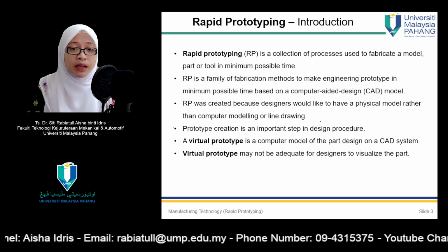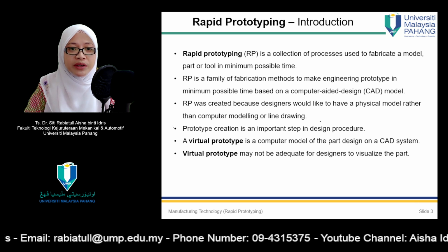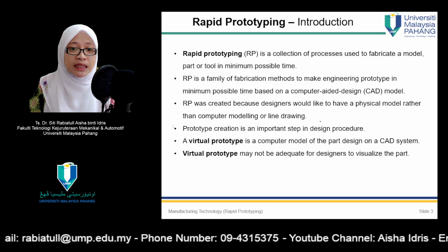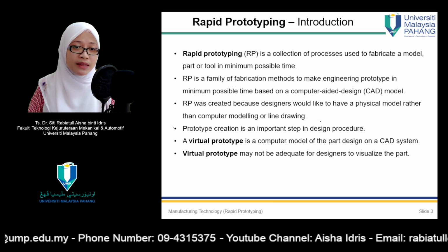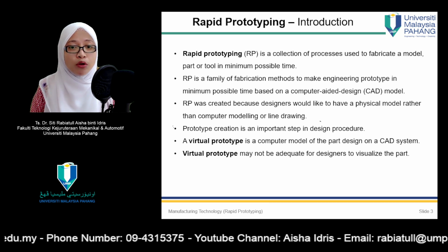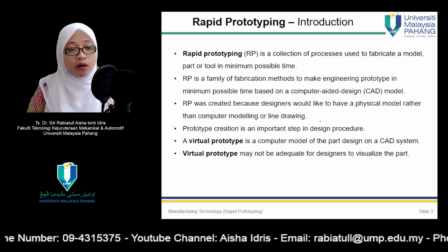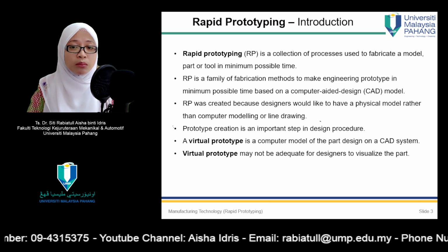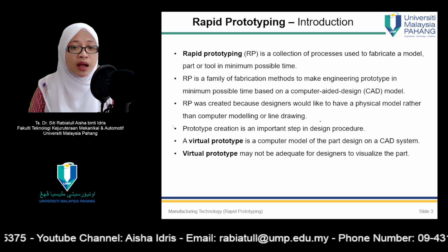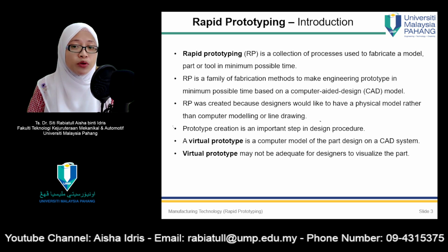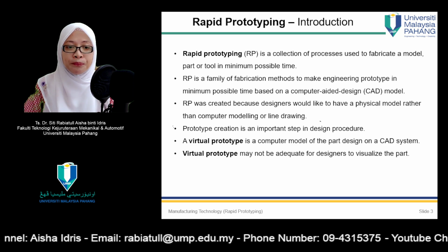The traditional method of fabricating a prototype part is machining, which can require significant lead times up to several weeks, sometimes longer, depending on part complexity, difficulty in ordering materials, and scheduling production equipment. A number of RP techniques are now available that allow a part to be produced in hours or days rather than weeks, given that a computer model of the part has been generated on a CAD system.